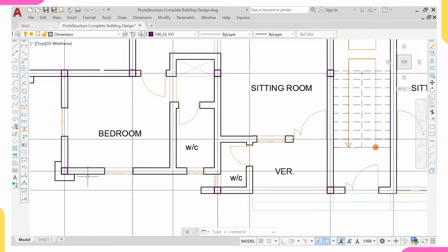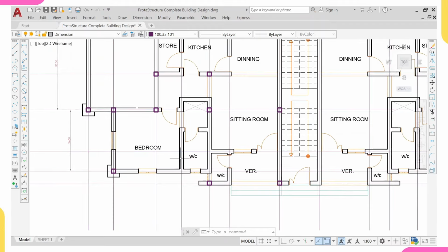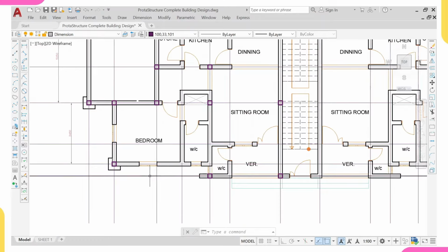And if you are placing a column here, you'll be having 2Y16. But since I've decided to have here as one beam, the whole of this length as one beam, that means the probability of you having 3Y16 has increased. But don't forget, it should not be more than 6 meters. Once it's more than 6 meters, if the moment is very high, it might require you to increase your beam depth, or you might not stay within Y20. Do you understand? So just limit it to 6 meters.